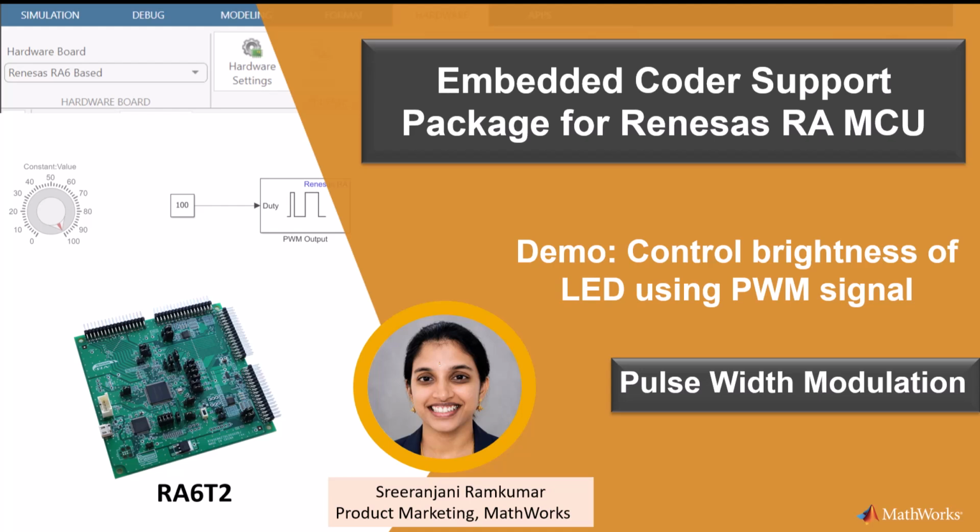In this video, I'll demonstrate how to configure the pulse width modulation block for the RA microcontroller in Simulink and use it to control the LED brightness by varying the duty cycle of the PWM signal. First, let's set up the hardware.